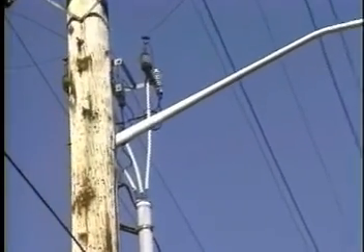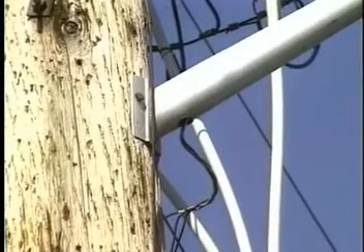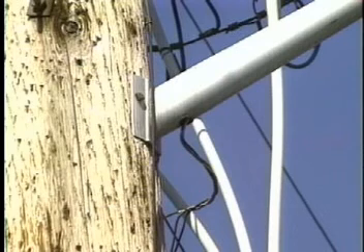Another critical point that is often overlooked is proper grounding of streetlights in close proximity to communication cables. Safety codes usually mandate that every light within 100 centimeters of a communication cable must be bonded to ground to reduce the possibility of personal injury should a craftsperson contact an energized streetlight case and grounded cable messenger.